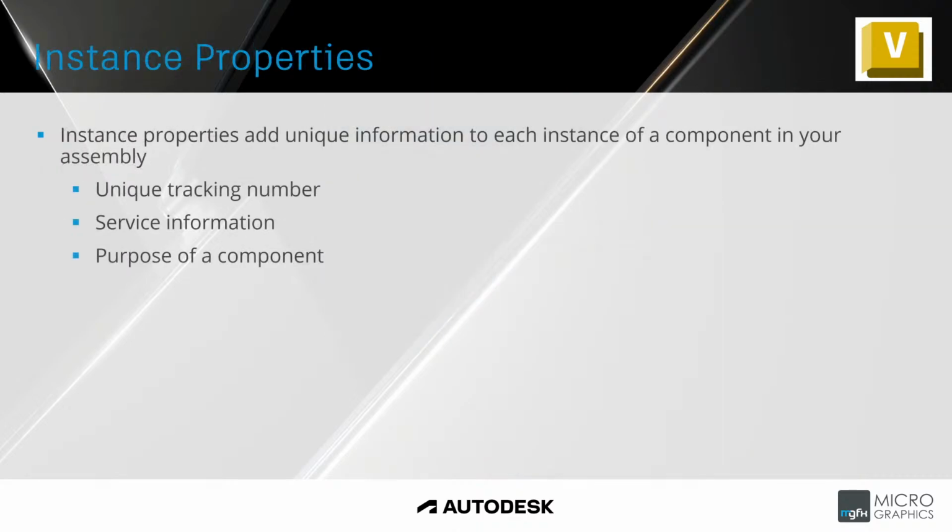Okay, so instance properties. Instance properties were introduced in 2022 when you got your model states. Now, what is an instance property? Think about if you've got an assembly and you've got 3 pumps in it, or 3 tanks. And maybe each tank has a different purpose. One's going to hold oil, one's going to hold water, and one's going to hold a gas of some sort. Now, with these 3 tanks, if you look at your bill of materials, it's all going to have the same part number. So it's essentially the same tank.